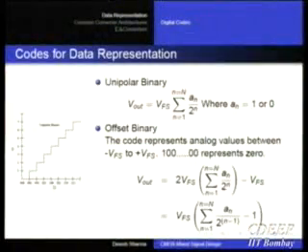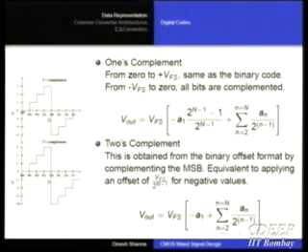So I express it as if it is binary and subtract VFS from it. Whereas the expressed binary number will go effectively from 0 to 2 VFS, the actually interpreted range will go from minus VFS to plus VFS. This is how I can handle the binary values as signed values.